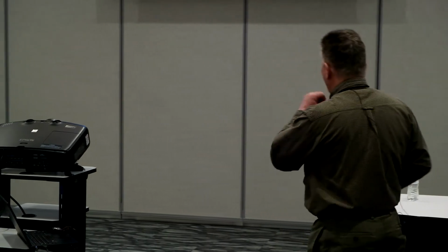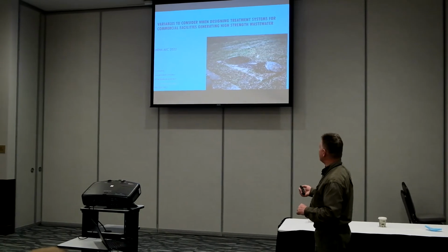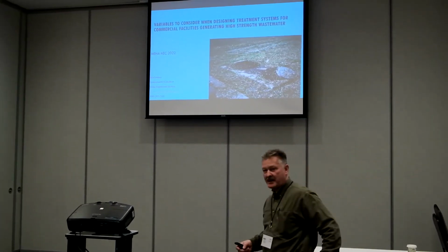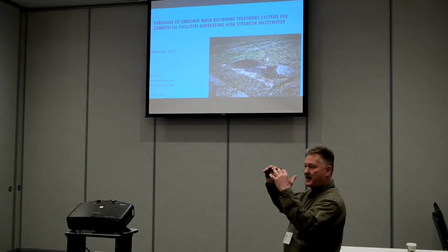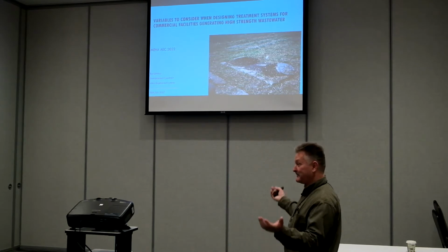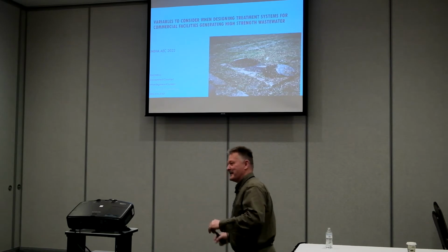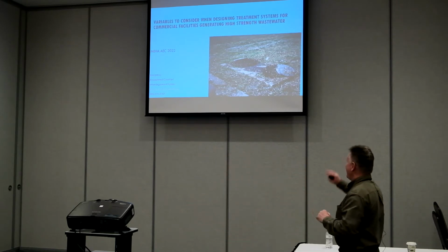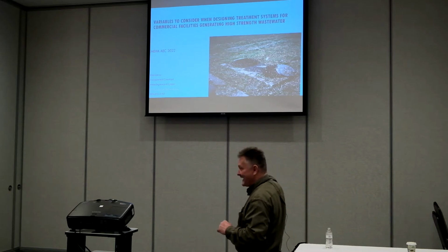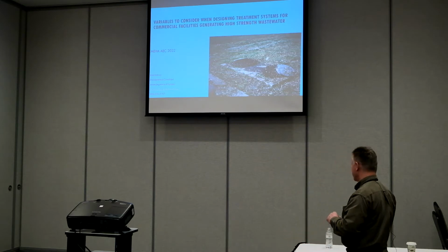So one of the first things that always comes to mind whenever somebody says wastewater is this picture right here of a septic tank with that scum layer popping up. Now, isn't that high strength? I mean, that's pretty strong wastewater to lift those 75-pound lids up. But that's not what we're talking about for high strength. Actually, in that particular condition, kidding aside, because we don't have any detention time, that is going to create high strength wastewater coming out of that system.